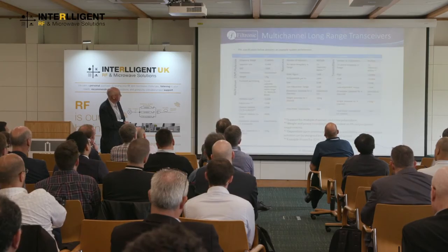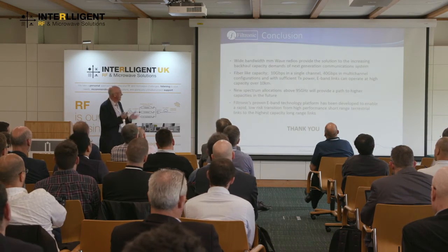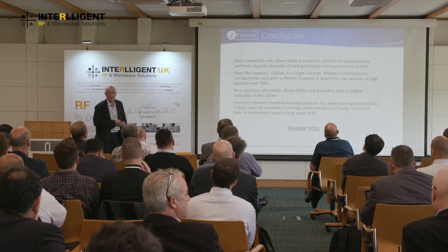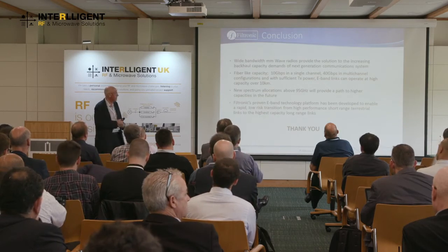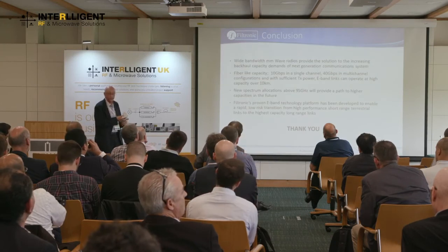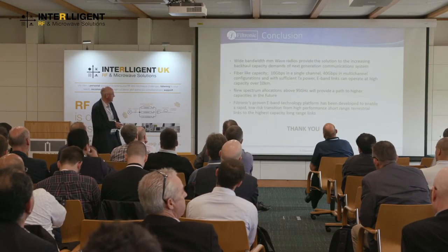I think I've probably run out of time. So basically, wide bandwidth millimeter wave radios will provide the solution to increasing capacity in the backhaul network. We're already demonstrating fiber-like capacity of 10 gigabit per second using single channels, and multi-channel systems will push that up to 40 gigabit per second. If we go to higher frequencies above 95 gigahertz, then the capacity can be increased even more.